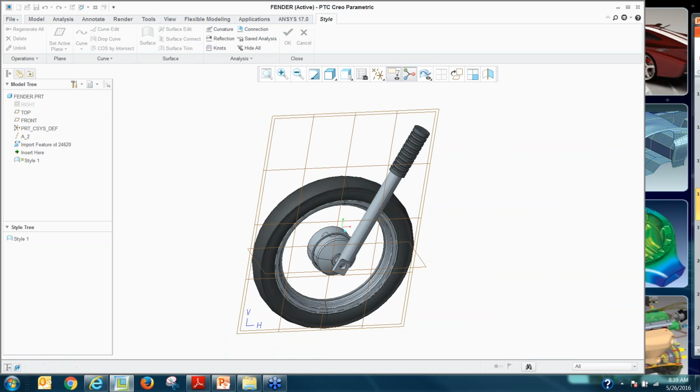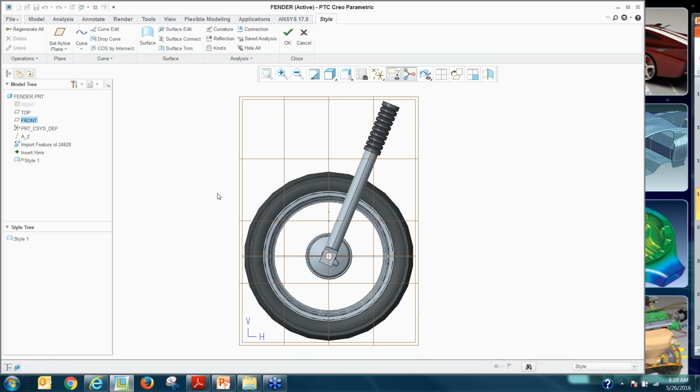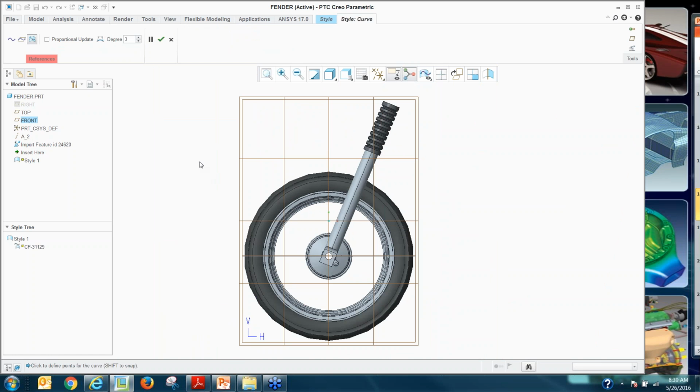I'm going to say that's my active plane, and I'm going to go to active plane orientation here real quick. And I can start throwing in a curve real quick, which could be a planar curve, for example, or a free curve. So I'm just sketching a spline. There it is, right? Something like that, right? And I can modify these.